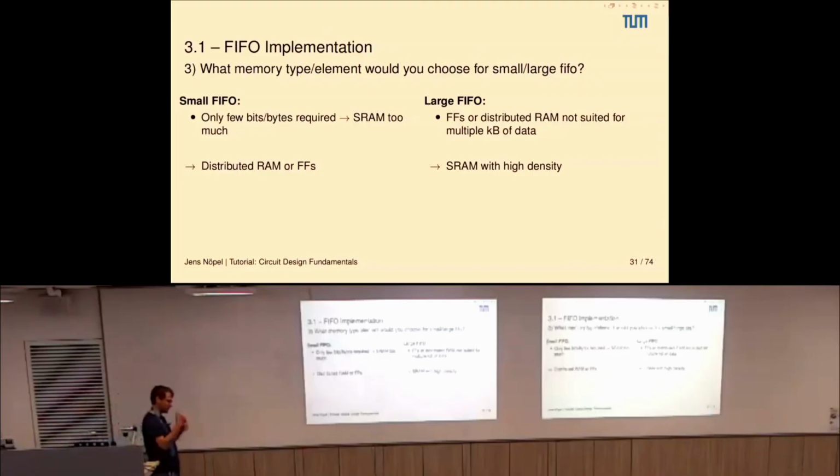So we can maybe also think of it from a different perspective. If we look at a flip-flop area-wise and compare how much area I need to store 1 bit in a flip-flop and how much area I need to store 1 bit in an SRAM cell, then the flip-flop is usually much larger than the SRAM cell.